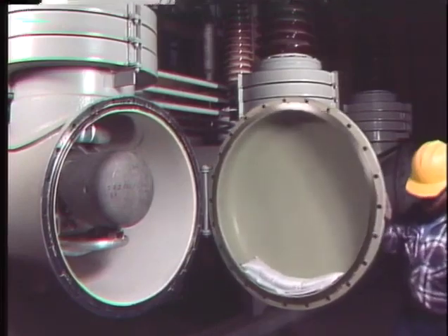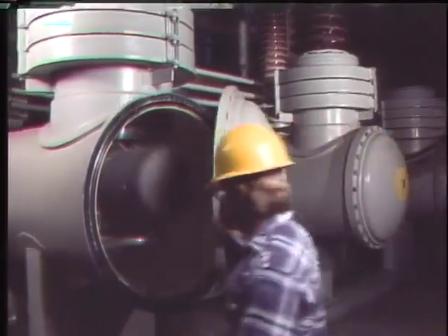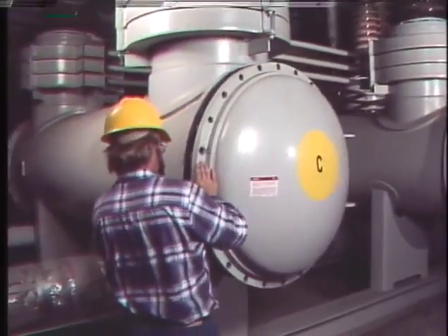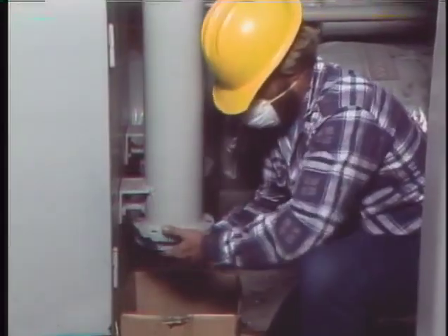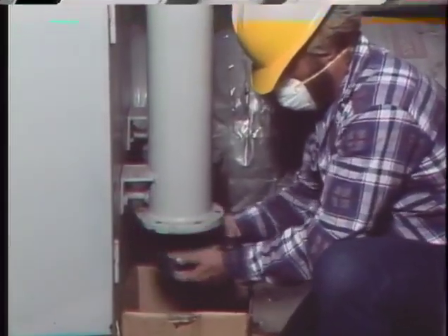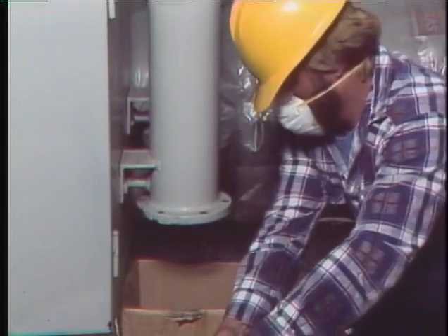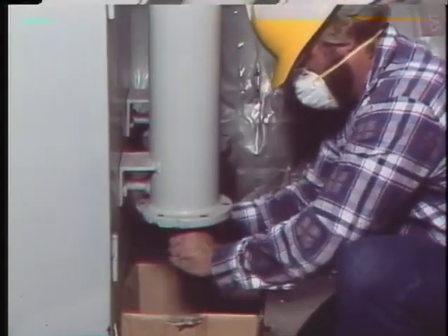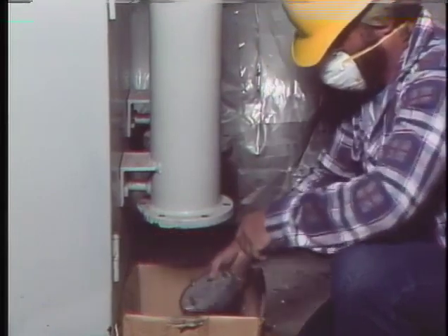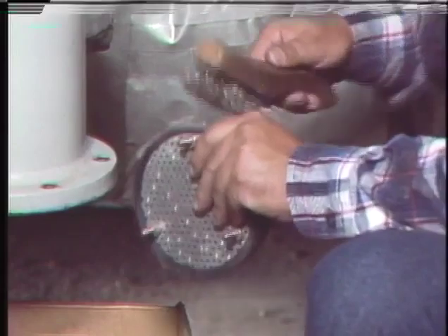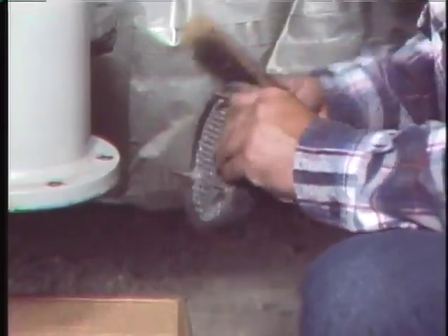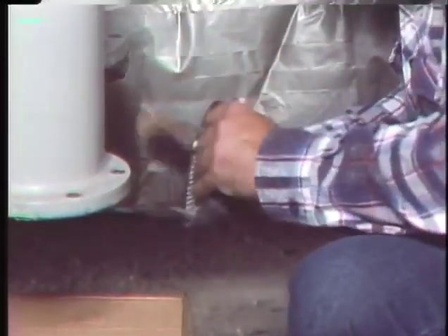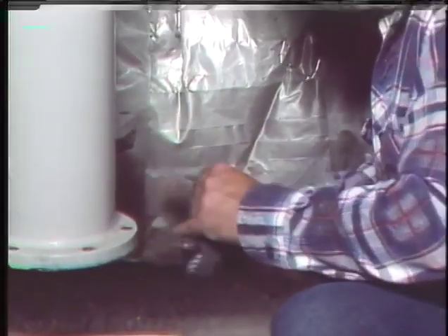After all the maintenance is completed, the breaker is closed up. Before gas is pumped back into the breaker, filters that remove moisture from the gas are serviced. The filters contain a desiccant, which is a granular material that absorbs moisture. The old desiccant is removed so that fresh desiccant can be put in its place. The filter also contains filter pads that prevent desiccant dust from entering the breaker. The pads are cleaned and put back in the filter.